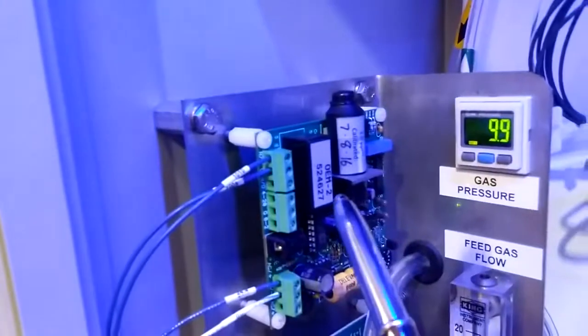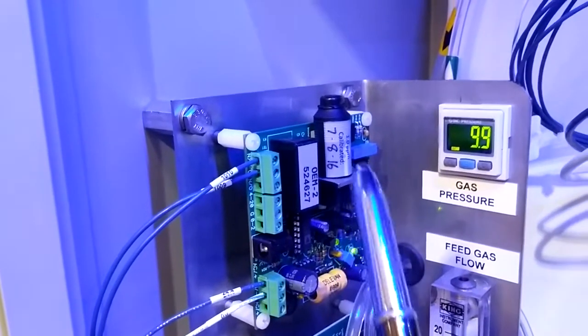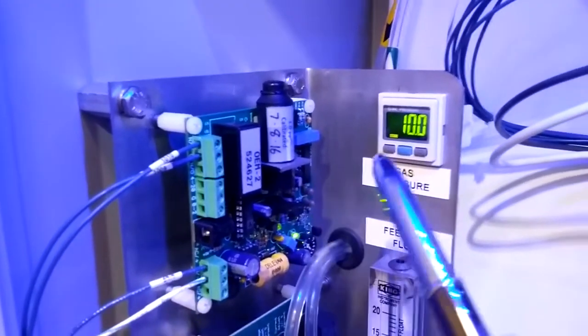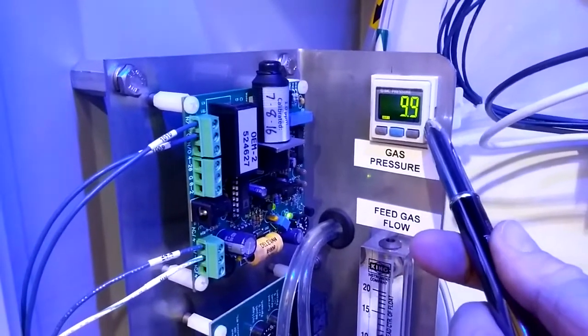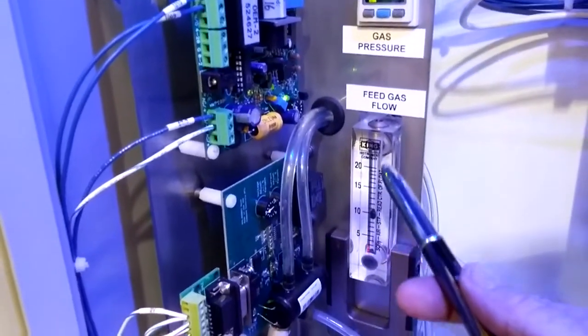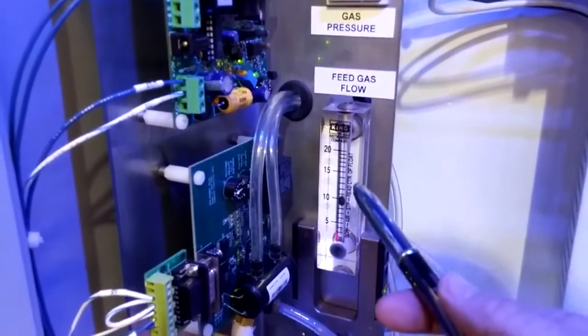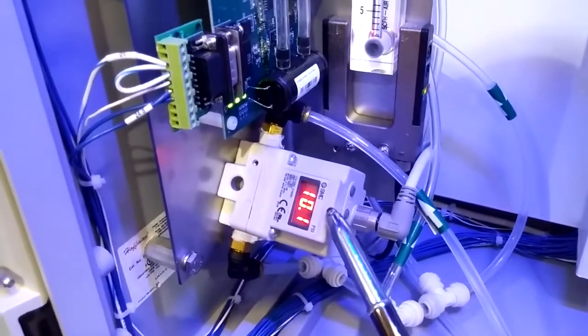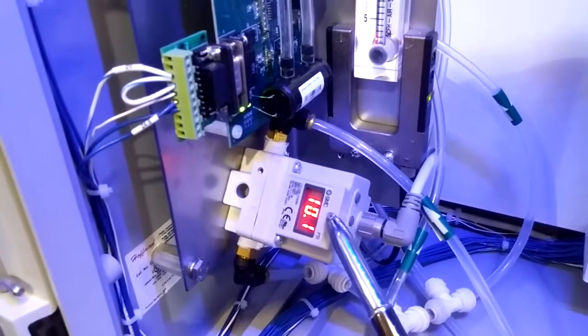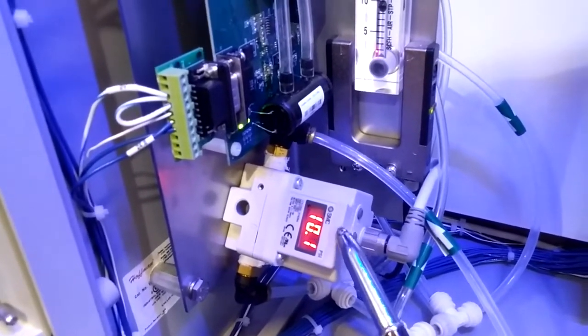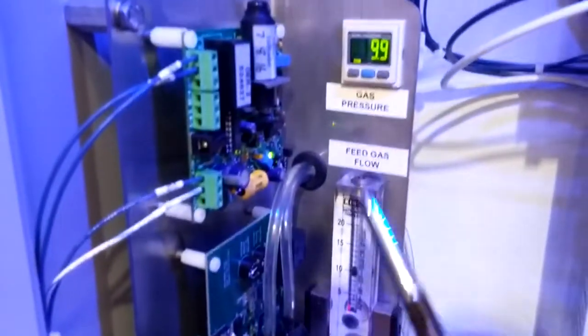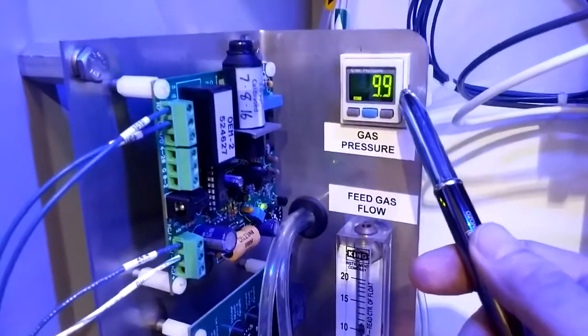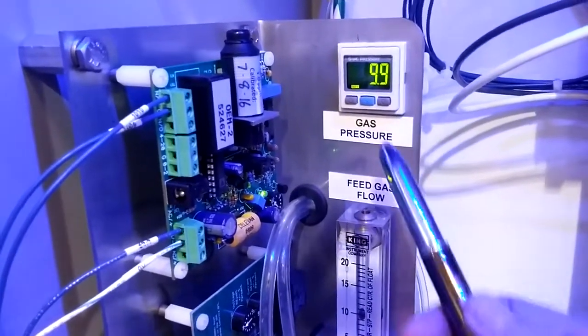Take a look here. On this particular generator, you can see we have the ambient ozone monitor that will detect any leaks in the system. We have our gas pressure for the system, that is the cell pressure of the gas. Feed gas flow tells us the current flow rate through the generator. Down here we have an electronic pressure regulator. This pressure can be preset from the HMI to specify the pressure we want for the system. If it drifts from that pressure, this SMC pressure sensor will detect that and trigger a fault if you're too far out of range.